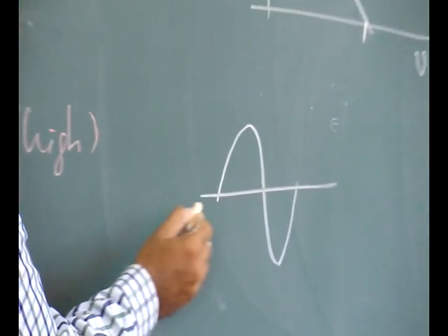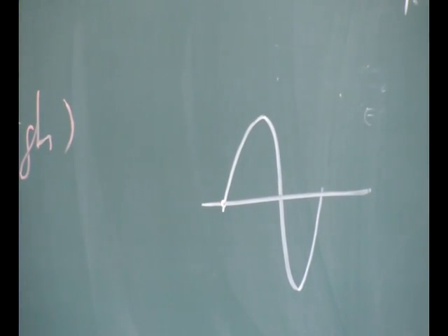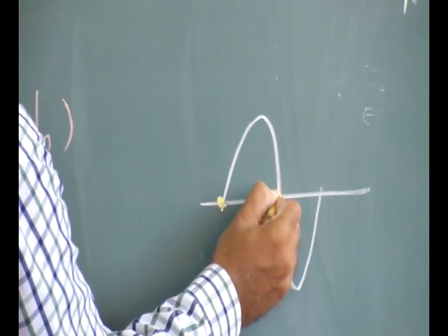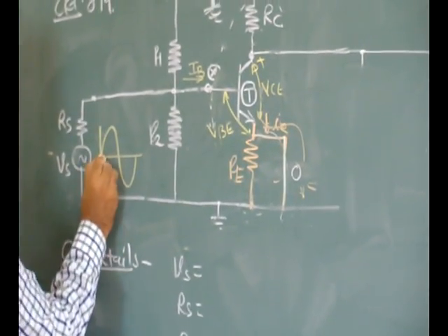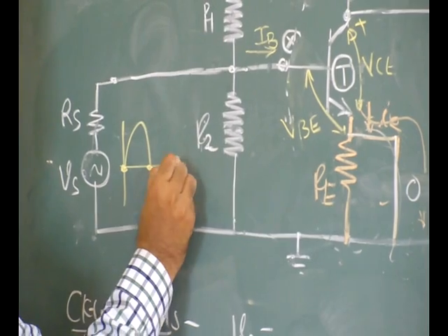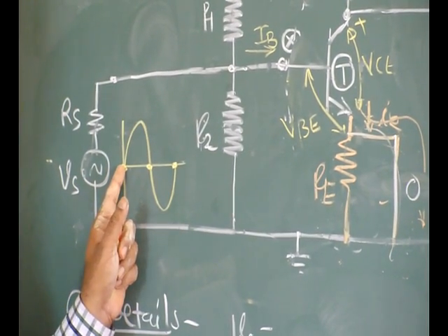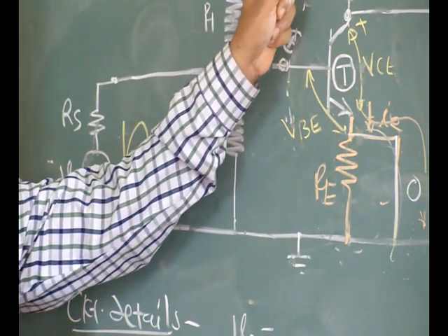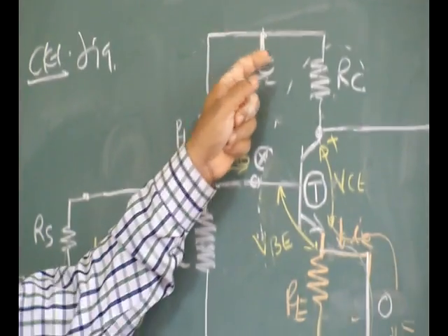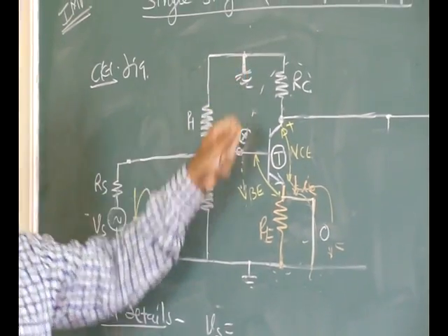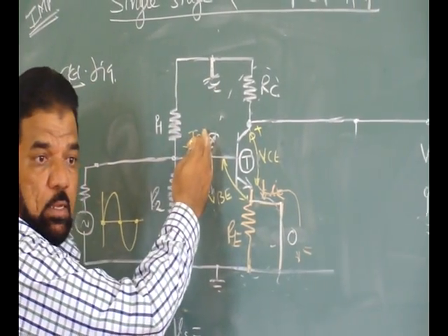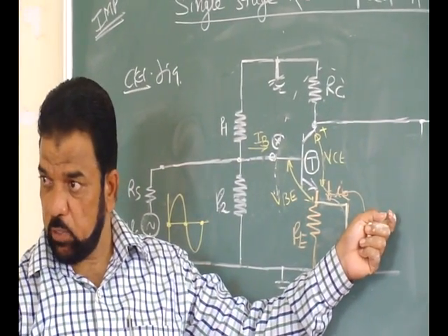If you think of this point very carefully, the points like this one, in this circuitry, if you have an input signal, now tell me the conditions at these points. What is the condition of the circuit here? AC is zero here, but still that DC is there. How do we short the DC? Only for analysis purposes. Practically we do not do this. I want AC analysis, so I will short the supply, then I will take the reading. Is that the way? Definitely not.